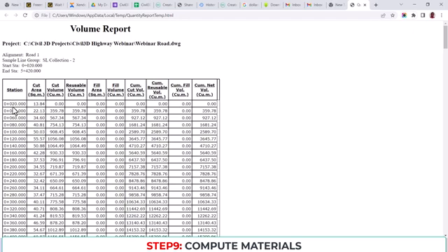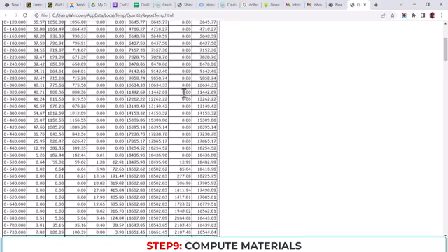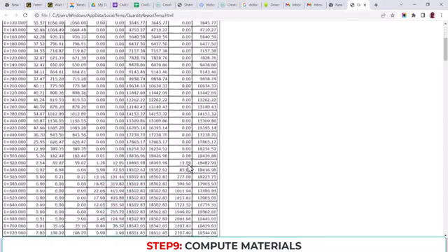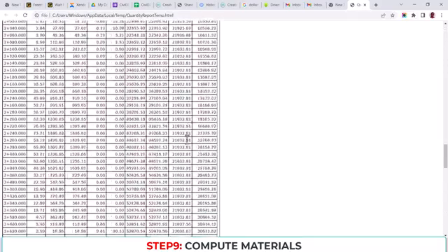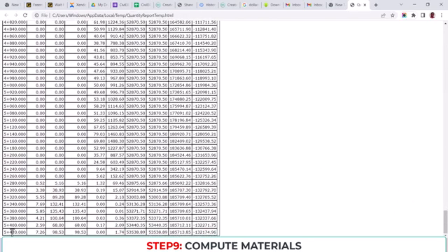As you can see, 00 is not showing because I told you in the sample line creation we did not check it for road 1. But basically you can see that we have our cut and then we have our fill. Somewhere here, all this way we are not having fill until somewhere here we have fill. So in the end, go to the last point, you will see that we are needing material. This minus 3 means that you need to fill.